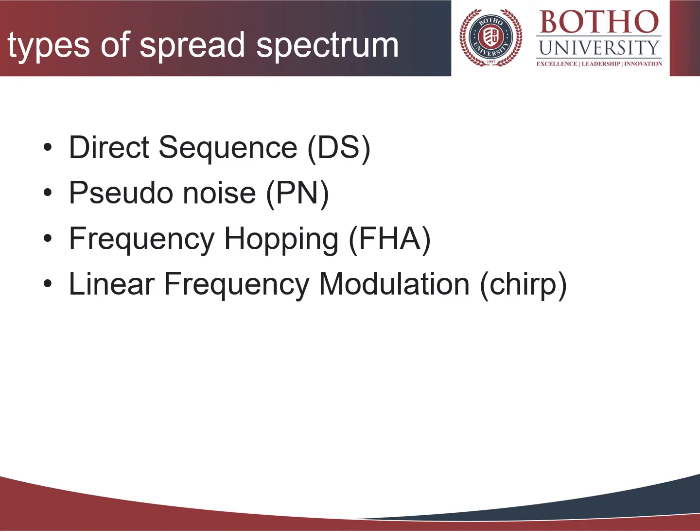The final one, which is called linear frequency modulation or chirp, is a signal in which the frequency increases, which is called an up chirp, or decreases, which is called a down chirp, with time. In some sources, the term chirp is used interchangeably with sweep signal. It is commonly applied to sonar, radar, and laser systems, and to other applications such as spread spectrum communications.